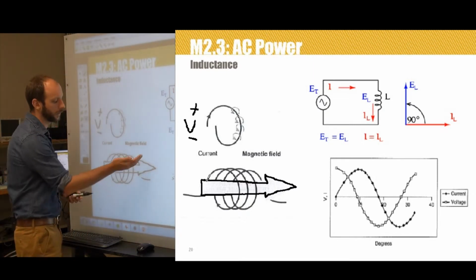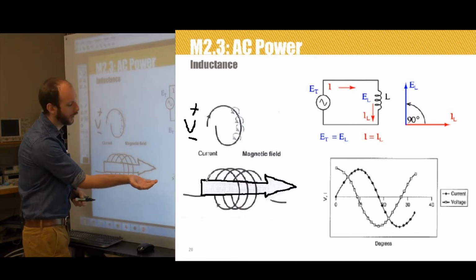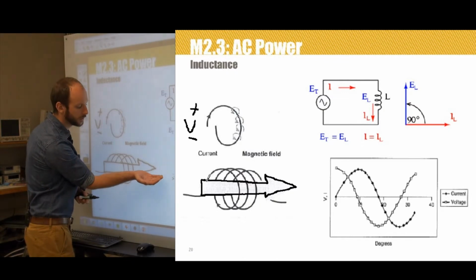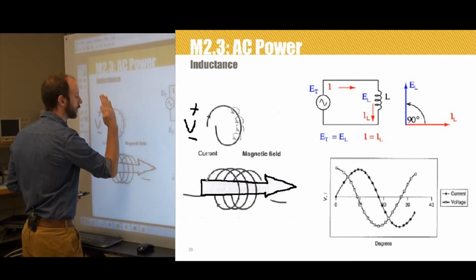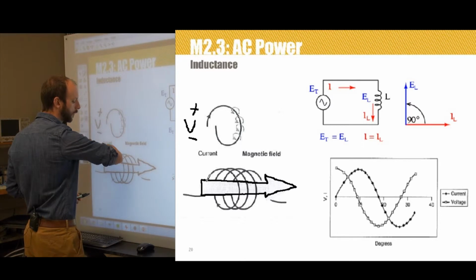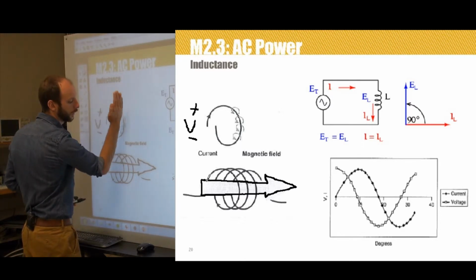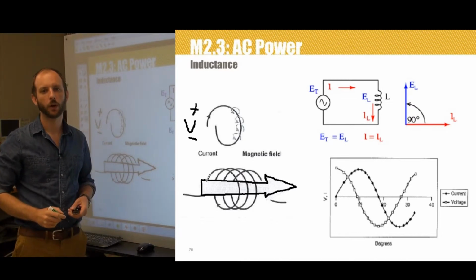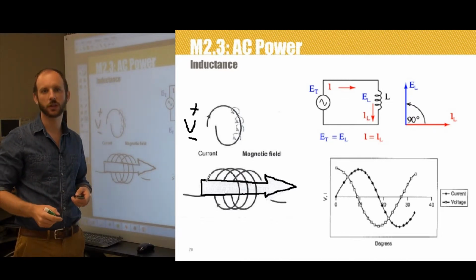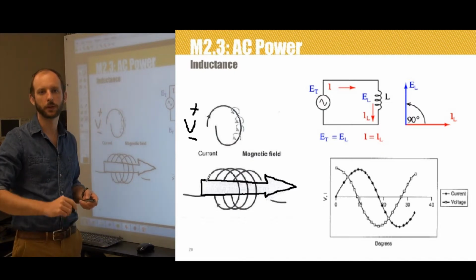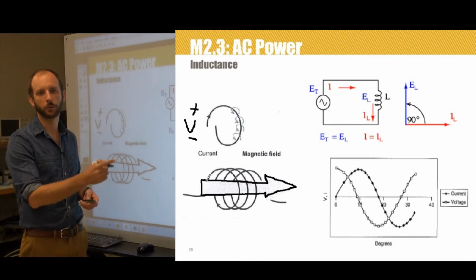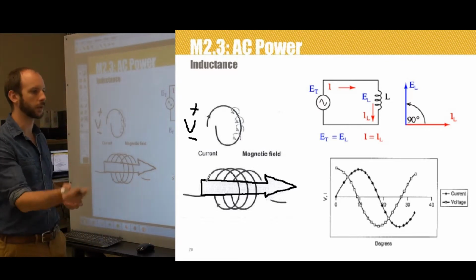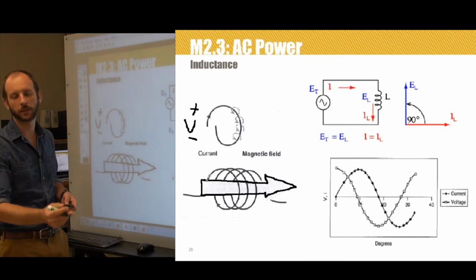At one peak, the magnetic field points in one direction, and throughout the AC cycle that magnetic field vector rotates until the zero crossing and then rotates back. It points in one direction at the peak of the positive half cycle, and rotates to point in the opposite direction during the negative half cycle. So we get what we call an alternating magnetic field.